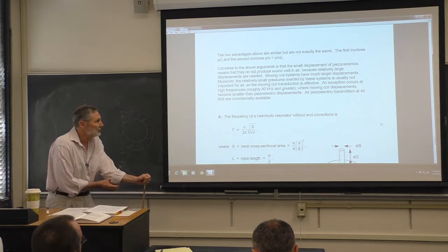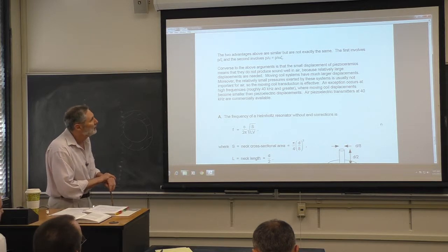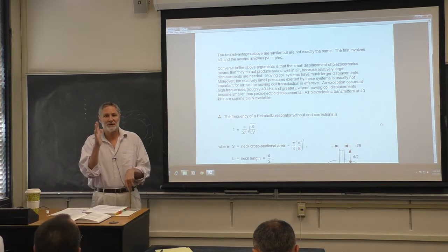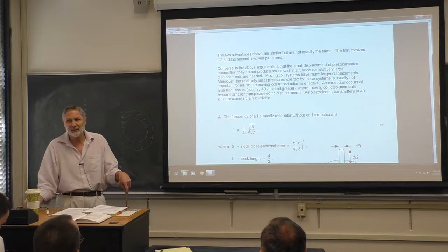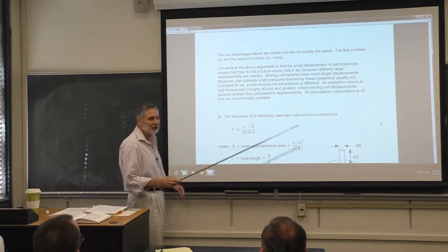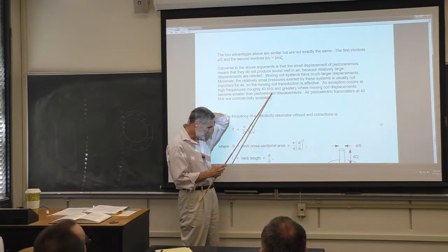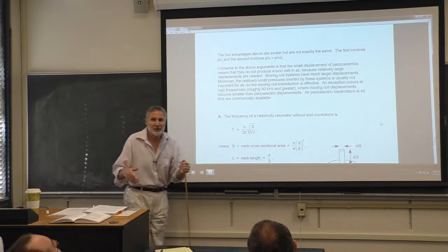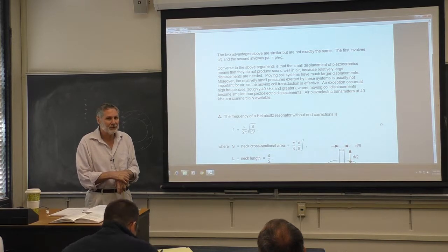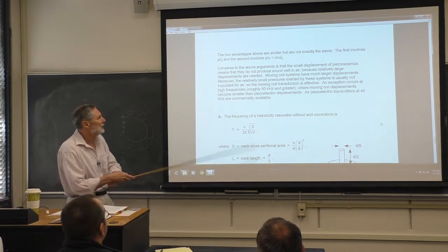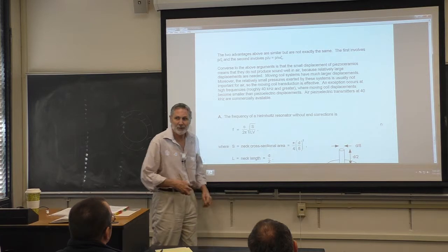Now there is an exception when you get up to around very roughly 40 kilohertz in air or greater. Now the moving coil technology, there's a mass moving there, and at such high frequencies the displacement becomes so small that they no longer become useful. And to be honest with you, we're going to find out about this, I think. I never really played with it. Even at 20 kilohertz, the limit of human hearing, there's not a lot of displacement there. So up there, it actually becomes more practical to go to piezoelectrics, and these do exist.